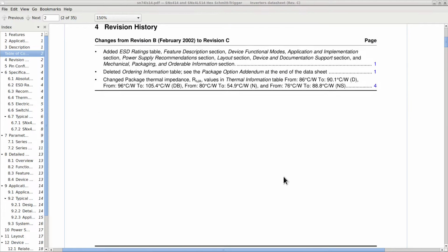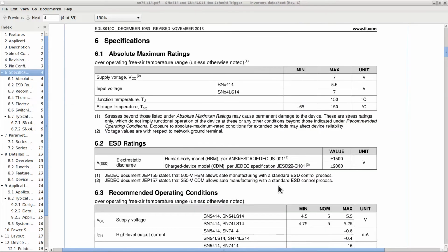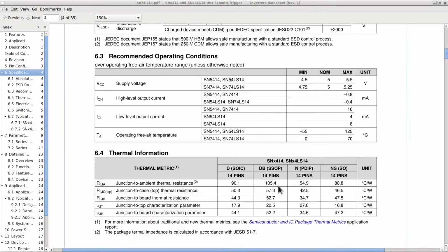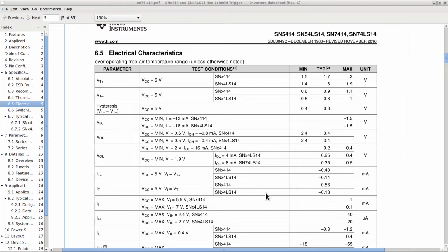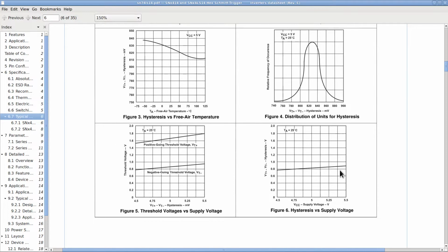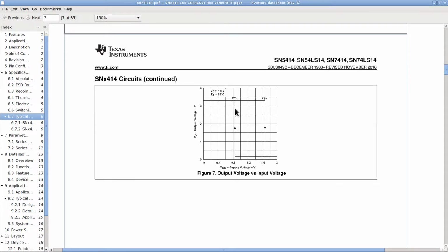The peculiarity of such a device is its capability of modifying an irregular input signal into a perfect TTL signal. It does that using at its input a voltage comparator that has 2 separate thresholds, usually named Vt plus and Vt minus, where Vt plus is greater than Vt minus. When the input signal becomes greater than Vt plus, the output of the device becomes a 0, and when the input signal becomes smaller than Vt minus, the output of the device becomes a 1.